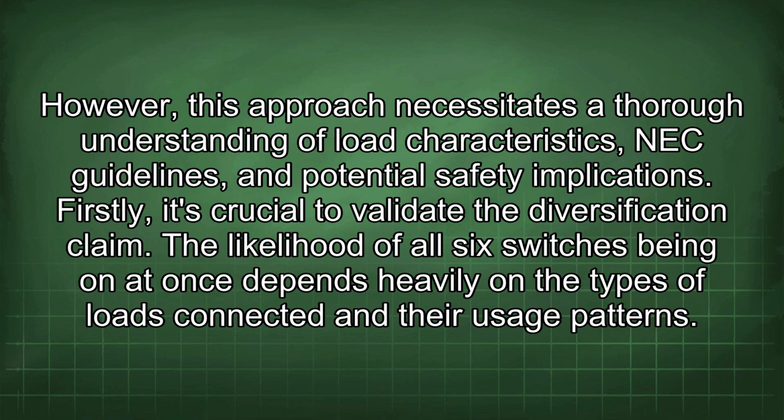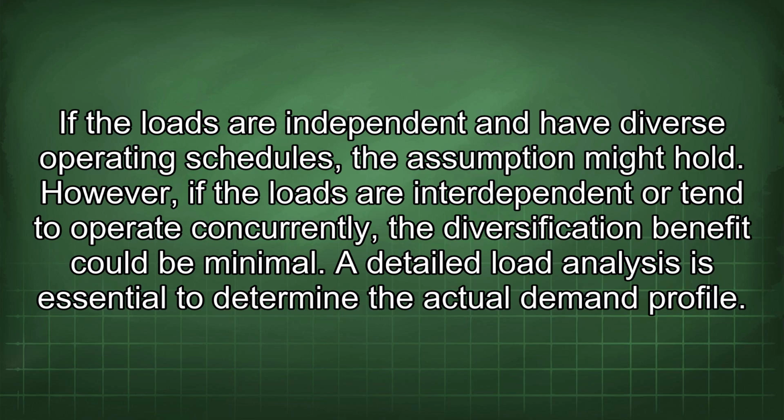The likelihood of all 6 switches being on at once depends heavily on the types of loads connected and their usage patterns. If the loads are independent and have diverse operating schedules, the assumption might hold. However, if the loads are interdependent or tend to operate concurrently, the diversification benefit could be minimal. A detailed load analysis is essential to determine the actual demand profile.